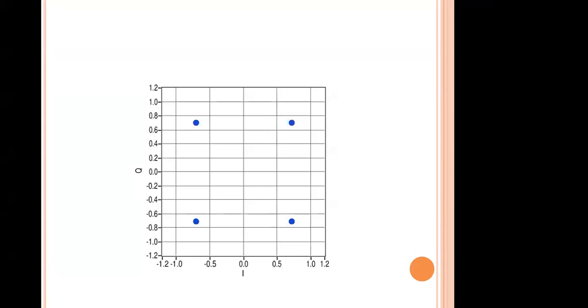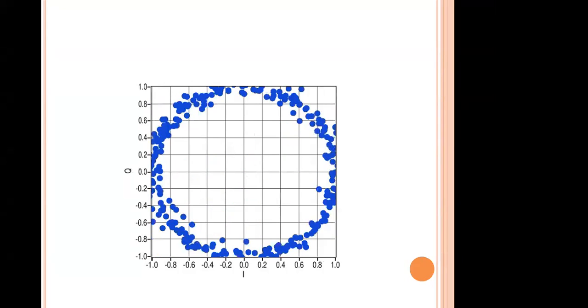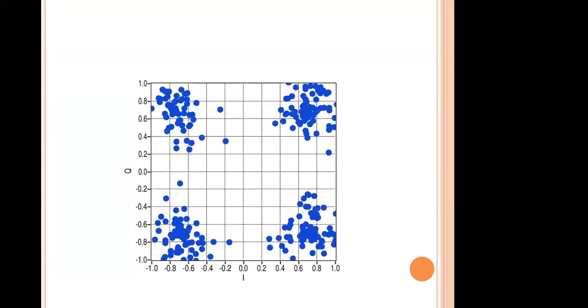So this is my transmitted constellation diagram and my received constellation diagram. I forgot to mention at what SNR this constellation diagram looks like. As the power is increased, the constellation points become localized to their respective positions. Even if you further increase the power levels, the constellation diagram is isolated to independent locations.